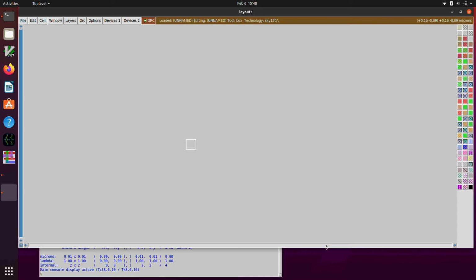So we're going to maybe do that. So now you'll see here we have a box, okay, and the way that we typically work in Magic is that that box defines an area, and we can paint some layer inside this box, and we can select stuff inside the box, and we can copy stuff inside the box.